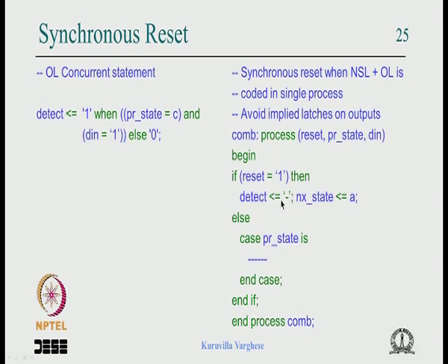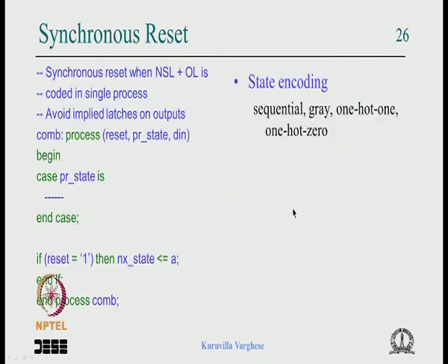You can say anything, it does not matter, detect is 0, it really does not matter, but to avoid that feedback, that latch, we say detect is 1. So you have to be careful when you combine the next state logic and output logic and include the reset, using synchronous reset. You can end up in this state and must write all the outputs here. If there are 4 outputs you specify all of them here. In this reset section you write the 4 outputs and say don't care. That is what you have to remember.